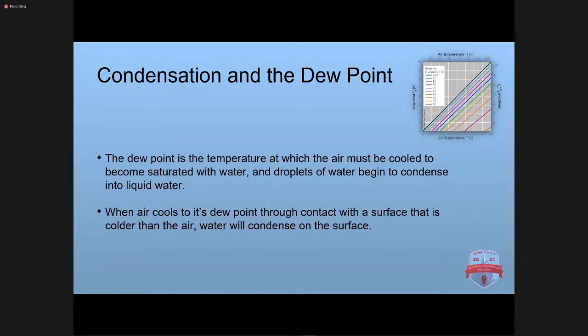The effect being that if you're drawing that warm air over something cool, you're going to start seeing condensation. If you've ever been in a place that's modestly humid, wearing sunglasses inside, you walk outside, all of a sudden your glasses fog up immediately. Why is that? Your glasses and the hot outside air have effectively reached the dew point on the surface of your glasses. So they're starting to collect the moisture that's in the air, and it collects on your glasses.